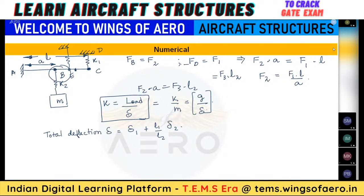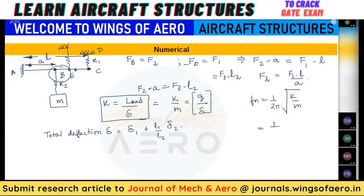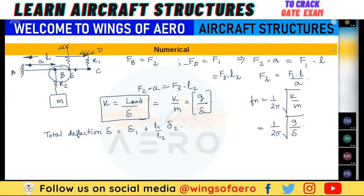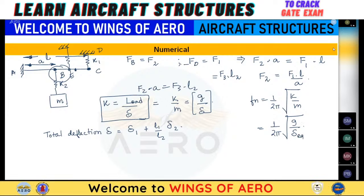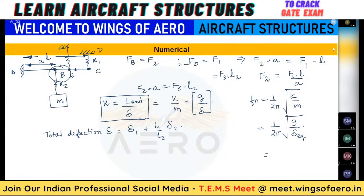We need to substitute back in this equation. So we know f of n equals 1 by 2 pi root over k by m, or we can write 1 by 2 pi root over g by del. There won't be any difference with the g. G is constant, 9.81. So we need to find the equivalent or the total one, and we will get the answer for that. Okay? Follow?